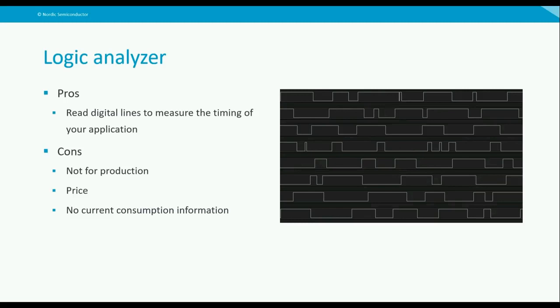It's definitely a valuable tool when your SoC is talking with sensors to see how traffic is exchanged and debugging your protocol, but it only gets us so far. Unfortunately, it's most often not very user-friendly on the final circuit board. They can be quite expensive, and they do not give any direct information about current consumption.